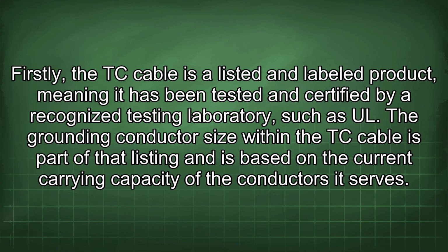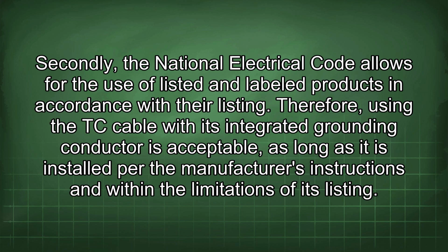Firstly, the TC cable is a listed and labeled product, meaning it has been tested and certified by a recognized testing laboratory such as UL. The grounding conductor size within the TC cable is part of the listing and is based on the current carrying capacity of the conductors it serves. Secondly, the National Electrical Code allows for the use of listed and labeled products in accordance with that listing.